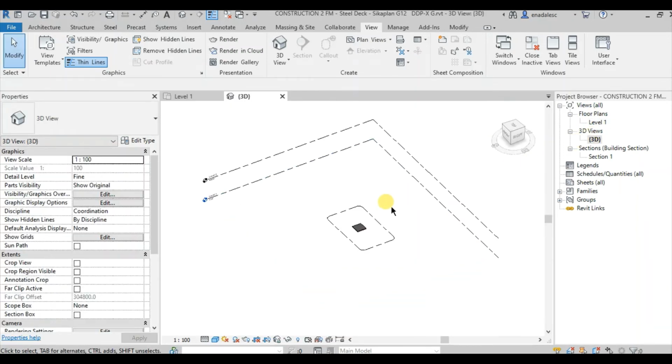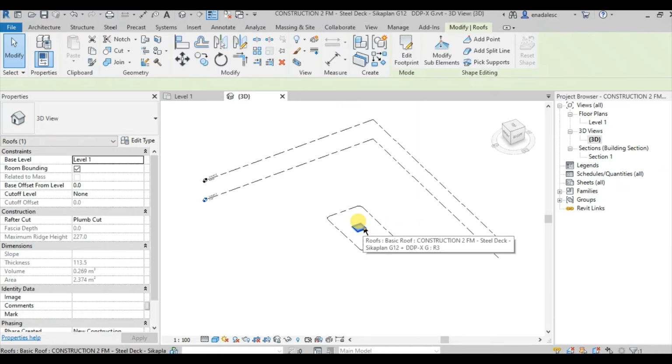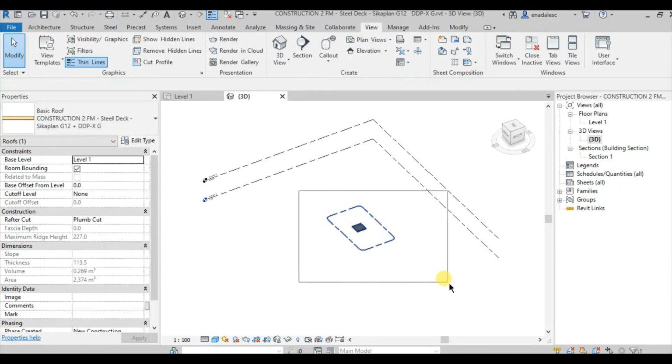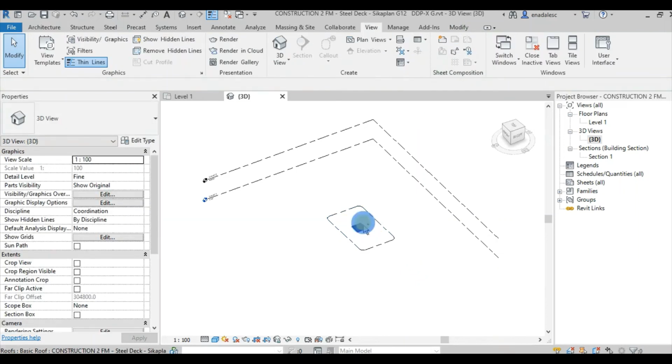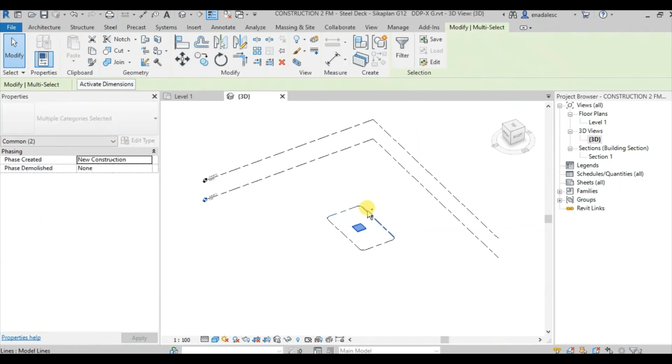Once we are inside a 3D space, we need to understand how to move in it with the mouse. I personally prefer to use a physical USB mouse rather than the touchpad, so grab one if you have it available, as it will ease the navigation around the 3D space. The left click is to select, and by dragging it you can make a wider selection with several objects within the selection frame. This is also possible by holding the Control key while left-clicking on each object to be added to our selection. To release that selection, simply press the Escape button.